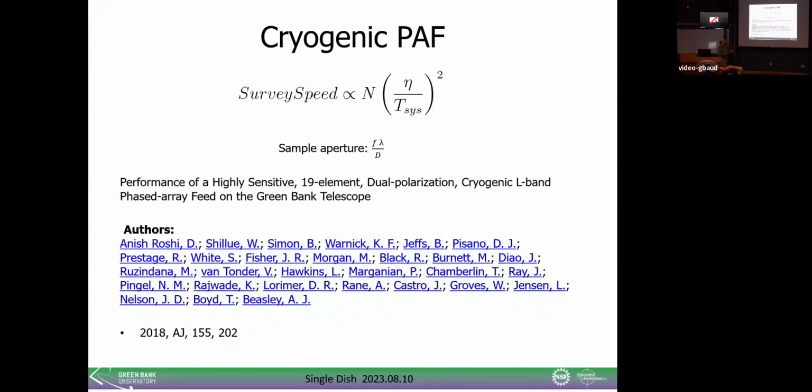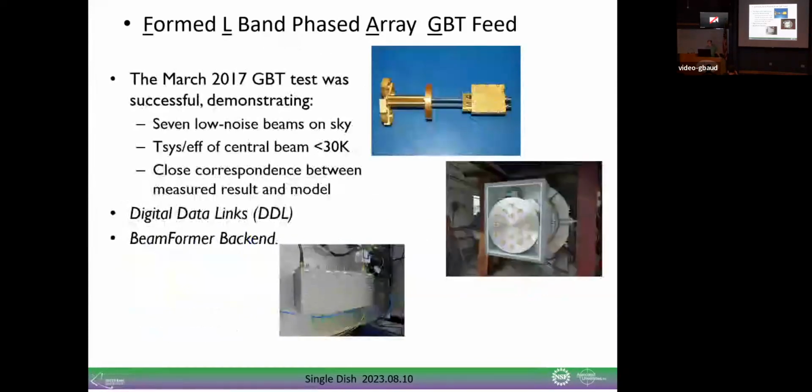You have a fully sampled aperture, so you don't have to worry about different mapping schemes to fill in the holes. You get one larger beam, scaled by the number of beams you're able to form. And so that's kind of the next wave of technology that is occurring now. I think the sweet spot is for K-band phased array feeds.